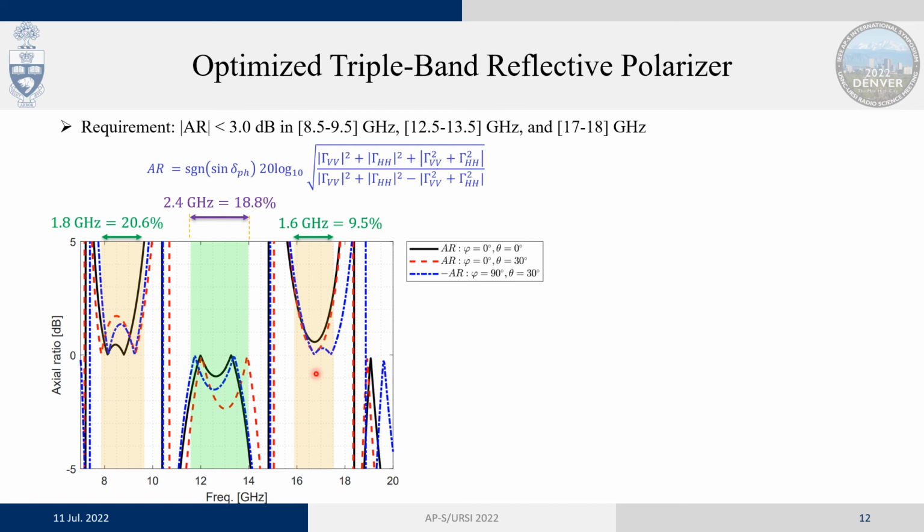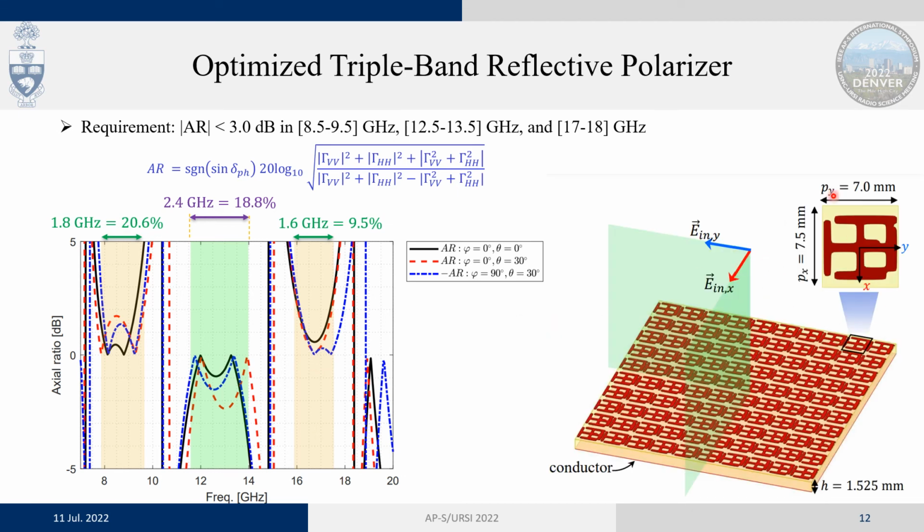of the reflected wave. Now, the structure or the shape of this scatterer looks like the one you can see here, where the substrate is RT/duroid 5880, and the shape of the scatterer almost looks like a Jerusalem cross, but it is judiciously engineered by the generator to represent this triple band axial ratio.